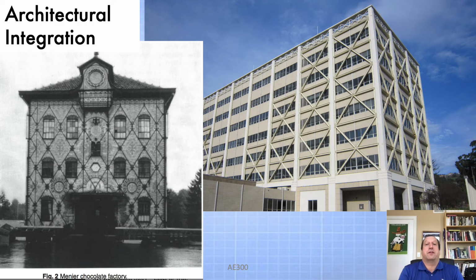Now, these X-braces are so obvious and clear signals that they're often integrated into the architecture. On the left-hand side, we have one of the first steel frame buildings that we know about. This is in France, I believe it was 1797. It's the only photo I've ever been able to get of it. And you can see the X-bracing being used here so that they could have a tall and narrow warehouse at the docks, and only have relatively thin masonry walls. So this is the beginning of that engineering design approach.